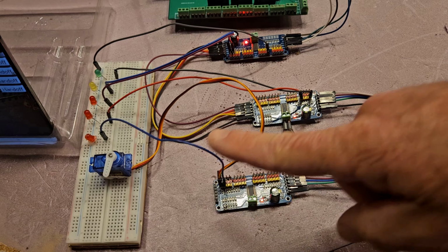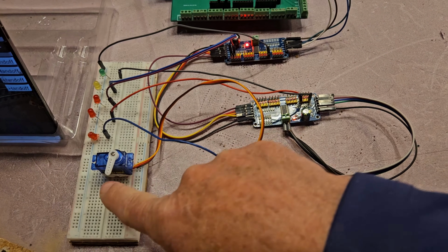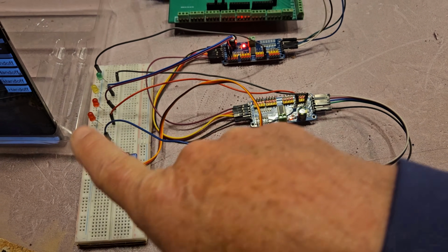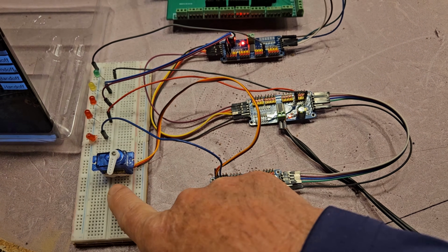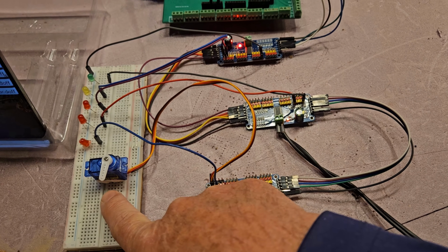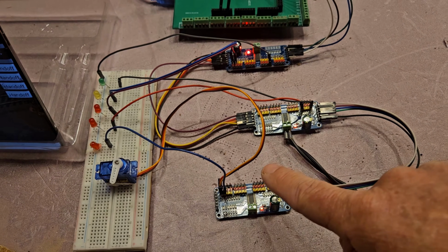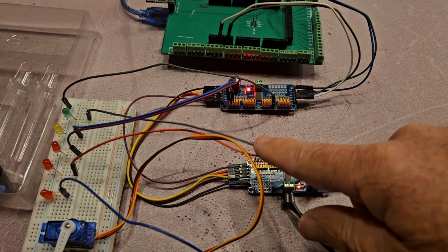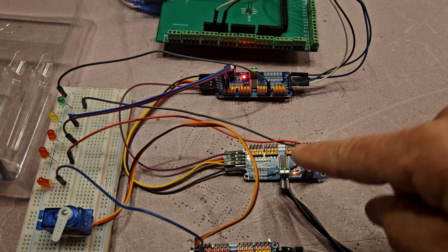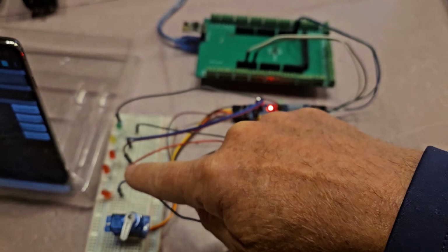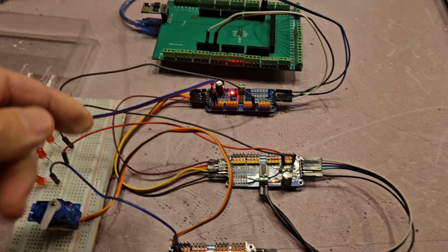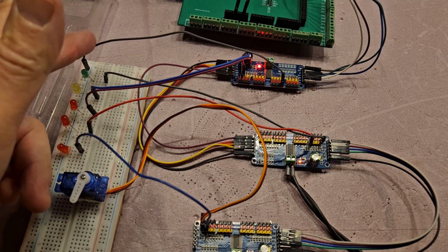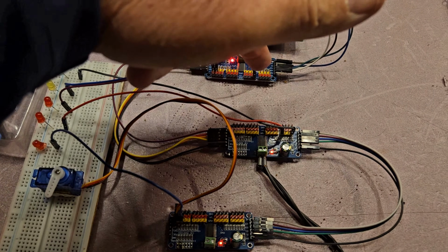And I've got a servo plugged into it. So like a servo controlled turnout, and an LED, which identifies the open or closed or thrown position of the servo. And right now it's in the closed position. You'll notice there's no ground connected here. And on this second board, which has 2 LEDs connected to it, there's no ground connected from all the LEDs, the common ground from all the LEDs. And I talked about that in the beginning of the video, that you can wire multiple LEDs together with just a single ground. It goes to the first board.